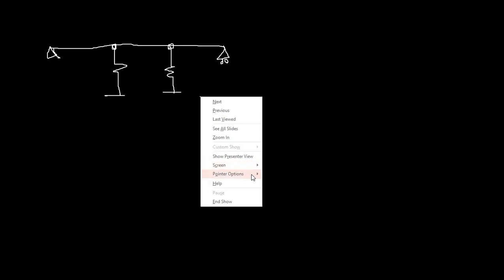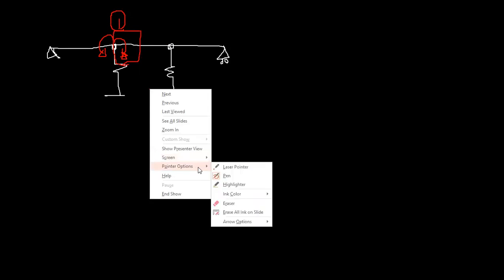Right? So if you apply a unit rotation and you are going to apply it at B, so we reduce the either way bending moment to 0. So we need to apply either way. So here clockwise positive, right? Remember, for that part clockwise positive, so in that case this is going to be anti-clockwise for this location, right? This is our first coordinate. For this part we consider clockwise positive, right? That's why we need to add a clockwise here to balance that. Actually at a joint it should be equal and opposite. That's why we add the other way around, right?